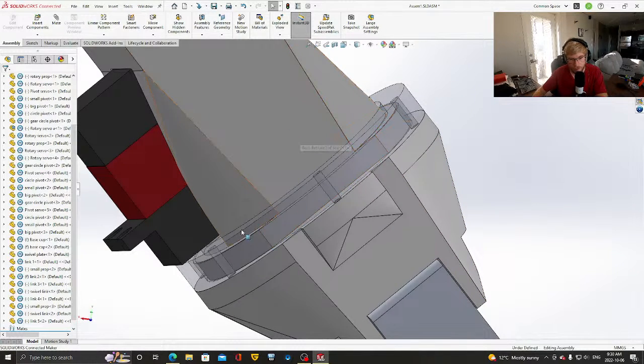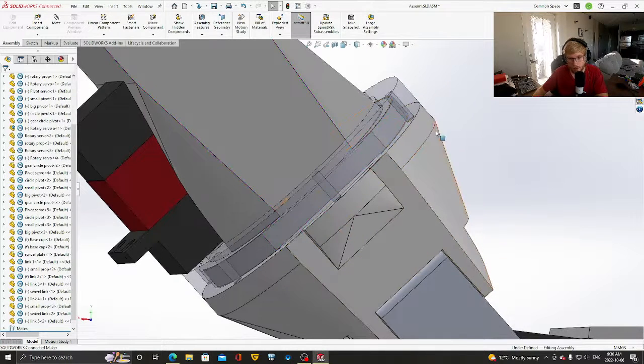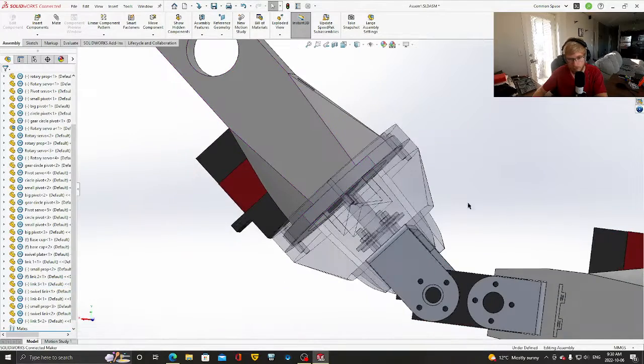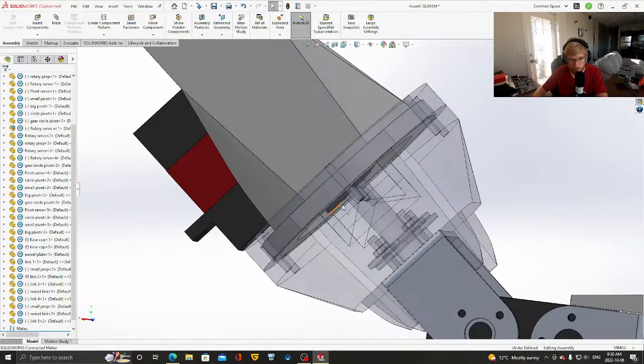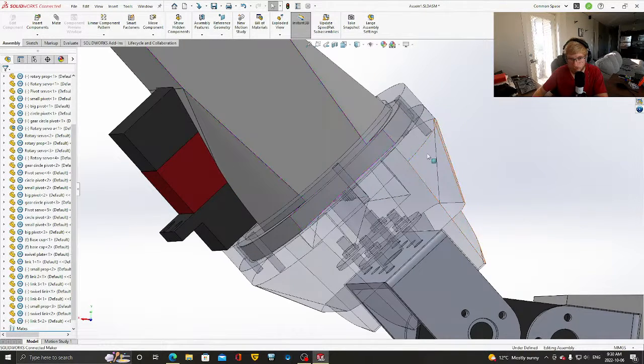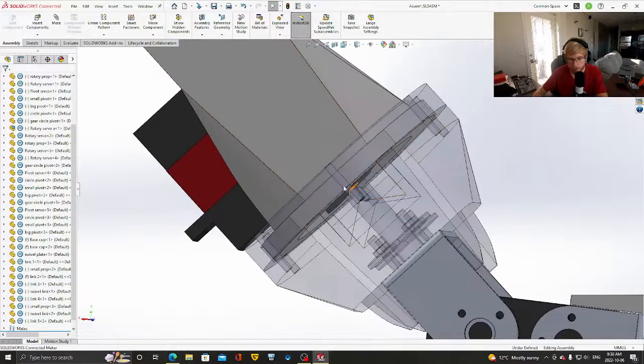So the end of the link goes to a circular extrude. And then I have this coupler link, I think I called it, or I just call it a swivel link. Basically, this swivel link will attach to the second joint. I'll make this transparent as well, so you can see there's the propeller of the servo. It is flush or flush enough with this front face. And then the secondary joint will ride along that front face attached to that servo propeller.